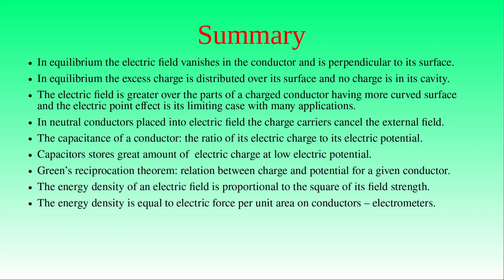Some measuring devices were also presented that apply the electrostatic force exerted on conductors, producing a deflection of a plate as in the case of Thomson's absolute electrometer, a deflection of a needle as in the case of the Braun electrometer, a deflection of a fiber as in the case of unifilar electrometers, or a deflection of a vane in the case of a quadrant electrometer. Since the deflection is proportional to the voltage applied on the electrodes of the devices, this voltage can be measured with a proper calibration of the device.